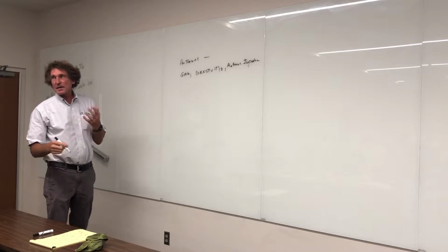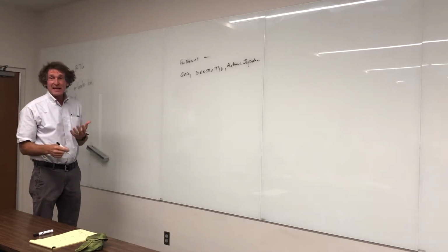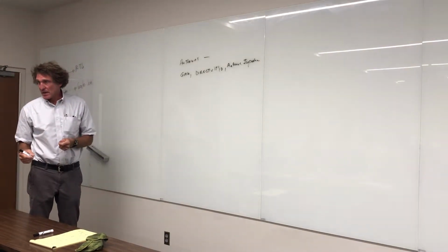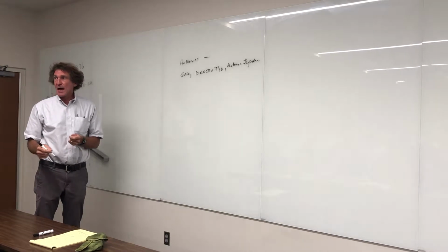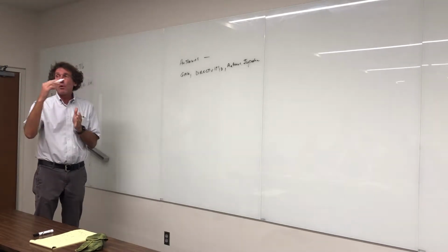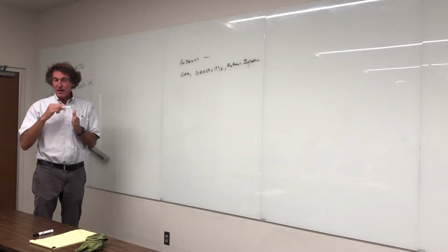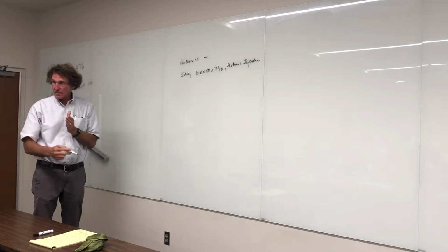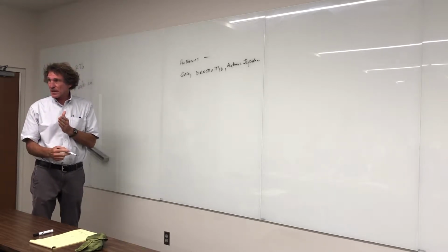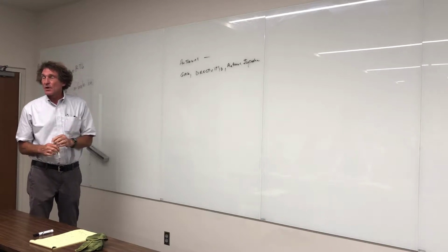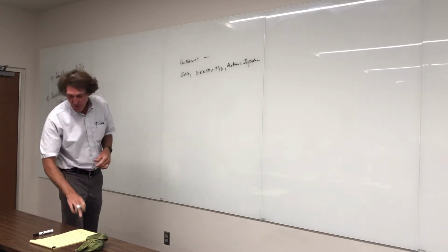So when you go buy an antenna, it has something called the gain. It's usually the maximum gain on it. And then it has something where it tells you how that gain's distributed. And it gives you a polar view, a polar pattern of where the maximum power density is and the minimum power density. These are called lobes of the antenna. Just keep this in mind so when we're going through this, you'll understand what I'm up to and why.